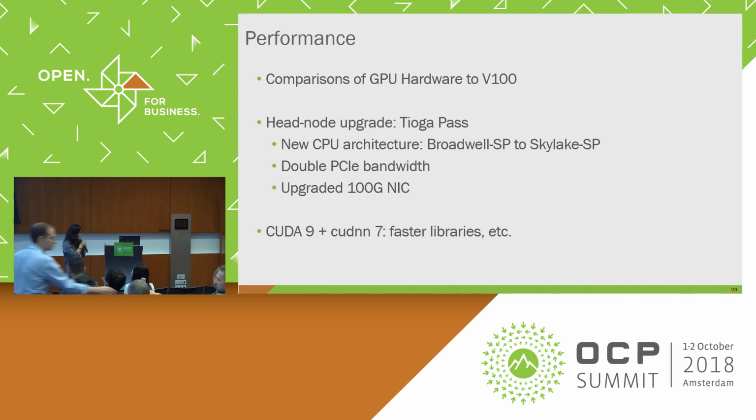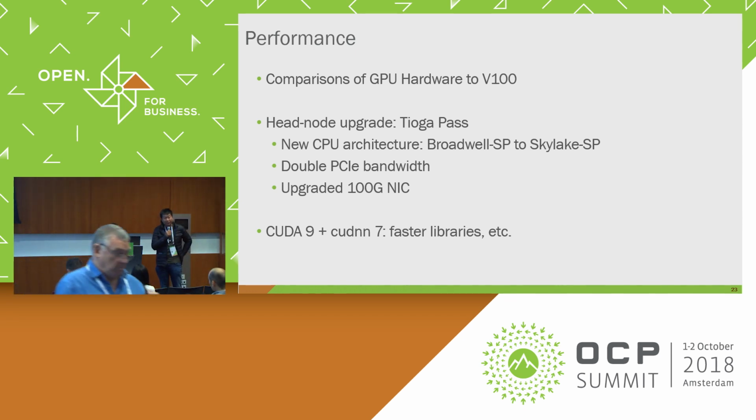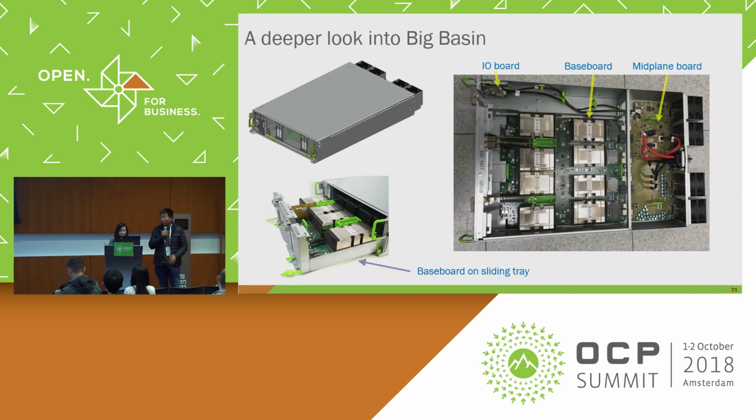I actually have Jacob, who is our thermal team leader here. I'm going to let him take it. So speaking about liquid cooling, we have an ACS group that is actually running to understand what the alternate cooling solutions could be for future platforms, especially for these generations. We are using about a 3U form factor heatsink, which is a pretty large heatsink that we could cool up to 300 watts, and it was actually workable. For the next generation, it really depends on how much the power and temperature requirement is going to be. That's why the whole ACS was created in OCP, to define the spec.